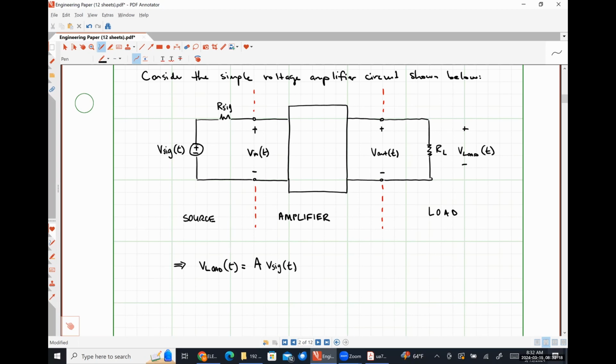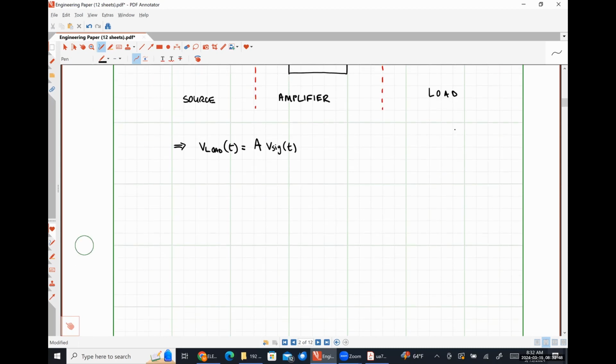Okay. So I already have a voltage source over here. So I'm probably not going to see another voltage source inside here, at least not when I'm looking in this particular direction. Everything that my signal source sees is going to be just some Thevenin resistance, which I typically call the input resistance of the amplifier. So if we redraw our circuit while we're piecing things together, we would have something like this.